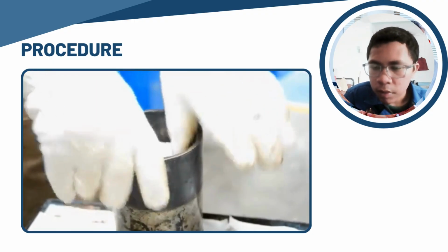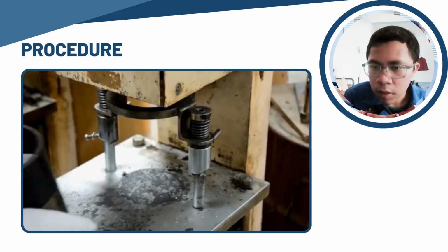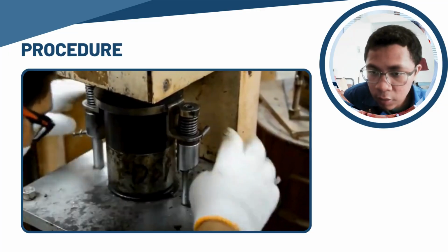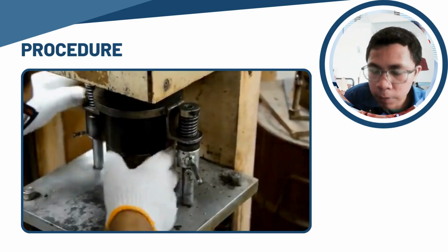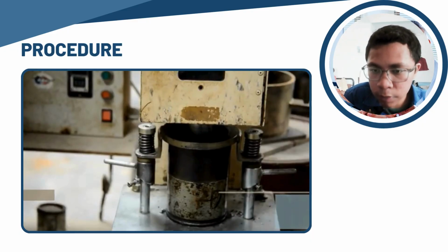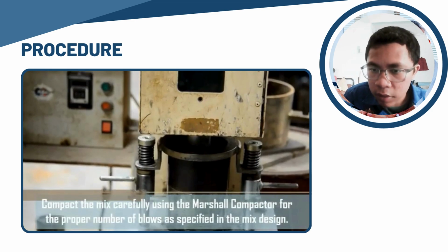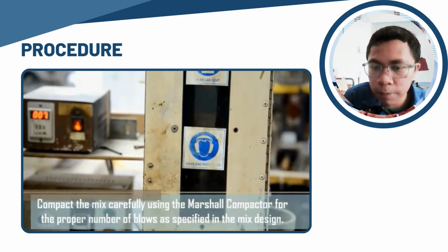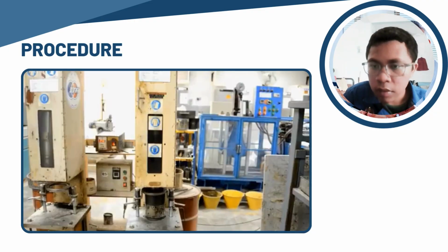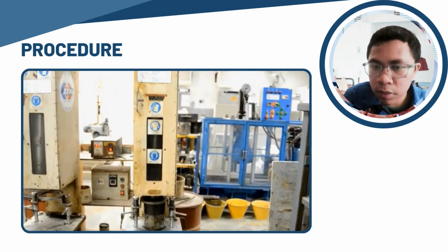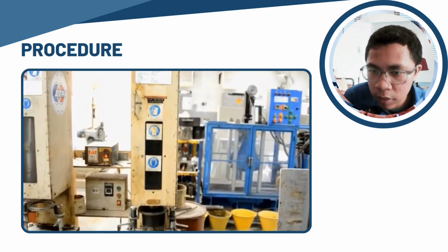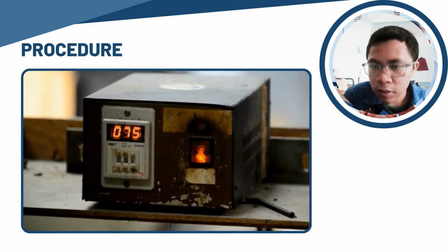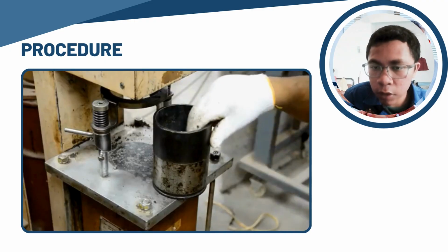minutes. Place the specimen in the Marshall testing rig. Load the specimen radially at a constant strain of 15.8 mm per minute. A trace relating strength and deformation is automatically recorded on a graph paper. Determine the stability of each specimen as the maximum load that the specimen could withstand. Apply correction to the stability values if required.